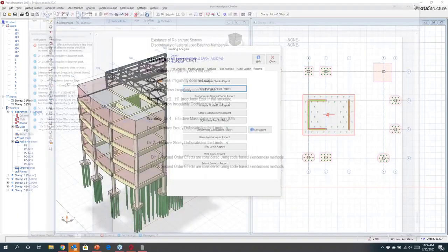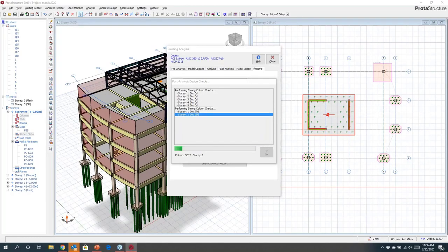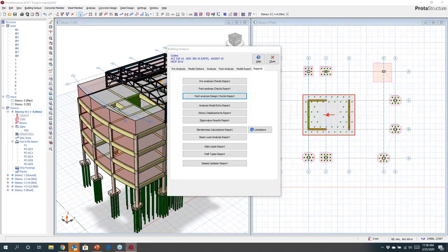Now, another interesting check is the joint shear as well as the strong column weak beam checks. And I'm just snapping through this because it's trying to look at the roof, which is steel. Again, it will produce a report that covers both joint shear checks that need to be satisfied, as well as strong column weak beam behavior. So this will all be designed and reported within the software, which you can use to check.